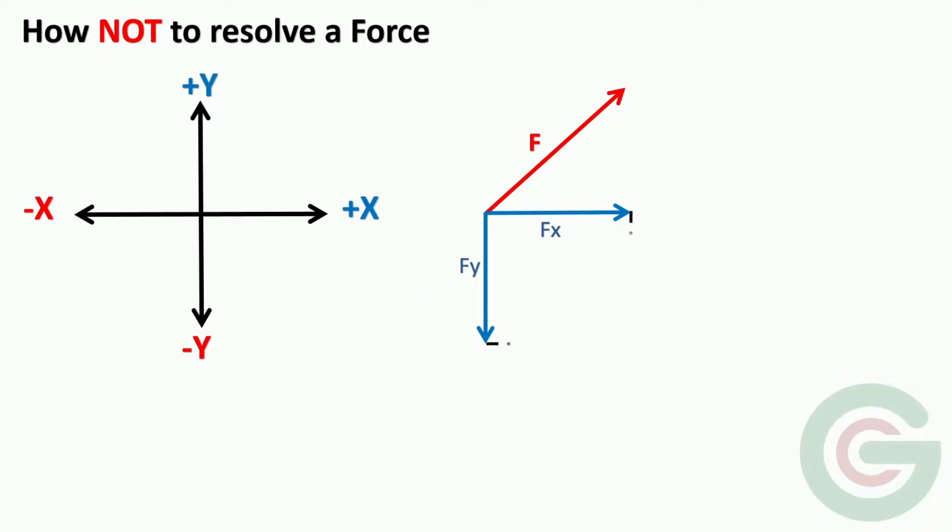Well, if you observe here, the resultant of the components is obtained in the fourth quadrant. Therefore, the directions taken are wrong. Now let's change the direction of the vertical component Fy. In this direction, upwards. Now if you observe, the resolution of the force is conforming to the parallelogram law. Hence, the directions of the components are now correct.